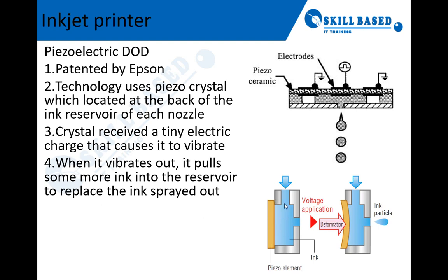Each nozzle is the same: we have a lot of nozzles per print head, and every fire exit has, instead of the resistor used for thermal, a piezo element, or piezo crystal. When the tiny charge is applied, it vibrates and expands behind, and it pushes left and right. As it moves left and right, the ink is fired out.